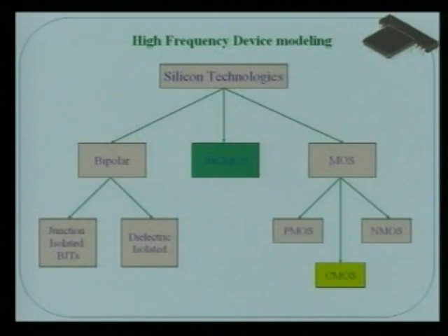So now for high frequency applications, for example, I want to make a few gigahertz oscillator, then sometimes I want to increase the gm value, that is the transconductance value. Transistors, the BJT, will provide higher values of gm compared to the MOS devices for a limited size, because you know that gm of a transistor is IC by VT.